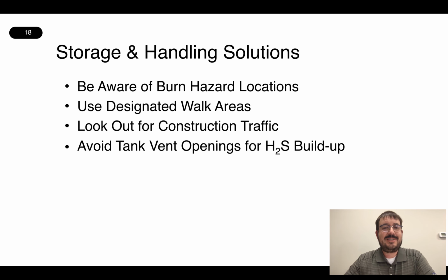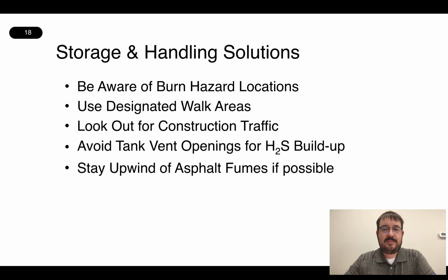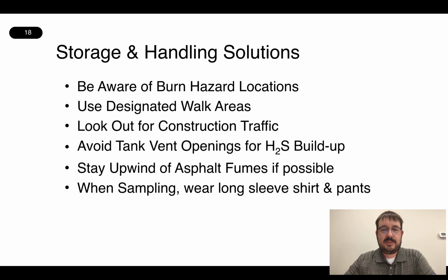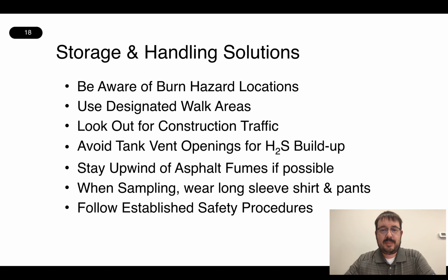It's important to avoid tank vent openings, particularly for H2S buildup. We always want to try to stay upwind of asphalt fumes if possible. And when sampling, it's critical to wear the necessary PPE. It's highly recommended to wear long sleeve shirts and pants, as well as gloves and face and eye protection to minimize any risk from asphalt burns from splashing or spilling. And as always, follow the established safety procedures identified by your safety personnel at your plant.